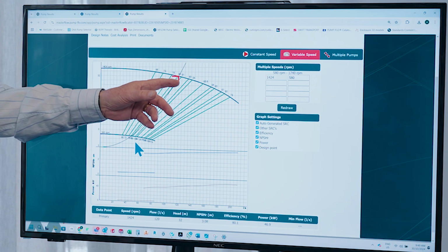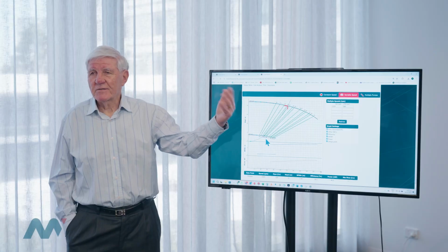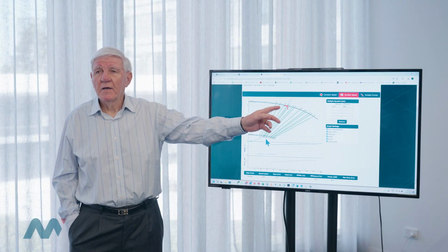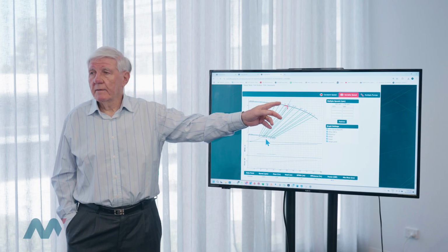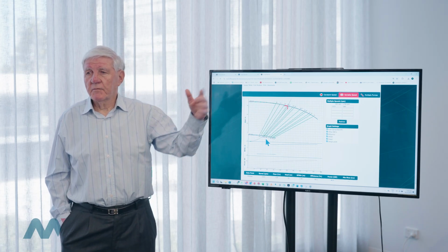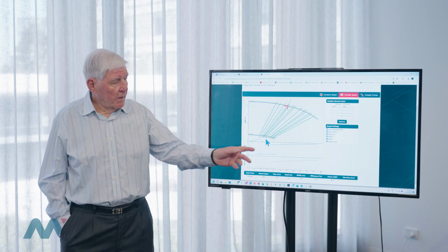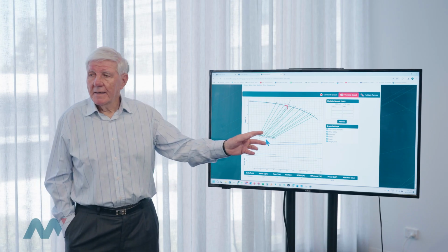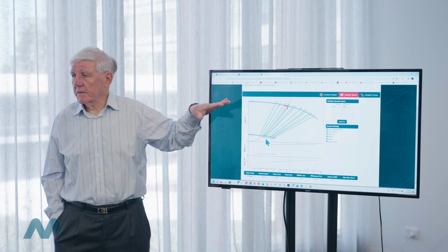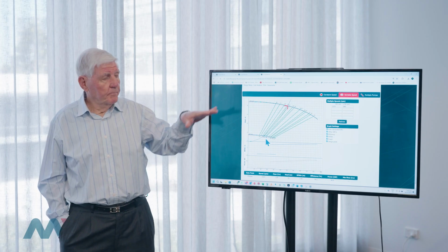It could be that this is the normal operating zone when it's the middle of summer or something like that. There's a very heavy heat load to handle, so they want a high flow. With that high flow, they will get a much higher system resistance. If they drop the flow back down because they haven't got such a heat load to manage, then you can operate at this point. And that's straightforward application of the affinity laws. So that's the effect of speed on flow and head.